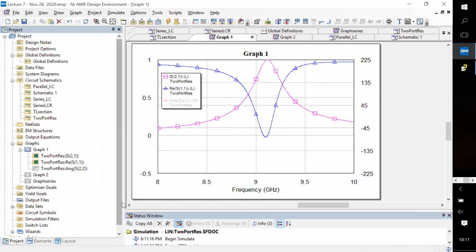So usually it's again full width, it's actually the 1 over square root of 2 points. It's the 3 dB points in power, which is not the same, which basically means 1/2 in power. And that would mean 1 over square root 2 in amplitude, because these are all, remember, magnitudes. So these are reflection coefficient amplitudes and not powers. Okay. That was basically it.